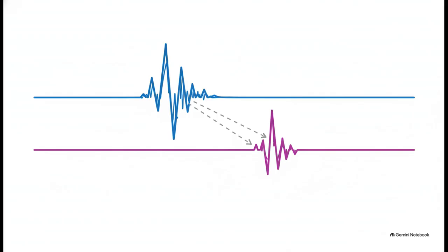Probably the most fascinating threat here is crosstalk. Imagine two microscopic wires running side by side. Because they're separated by an insulator, they literally act like a capacitor. If one wire, which we call the aggressor, suddenly spikes its voltage, that electrical coupling can inject a noise spike right into the neighboring victim wire. This crosstalk is so powerful, it can actually flip a digital 0 to a 1, or completely wreck the delay. This is exactly why engineers obsessively calculate wire spacing and routing direction.